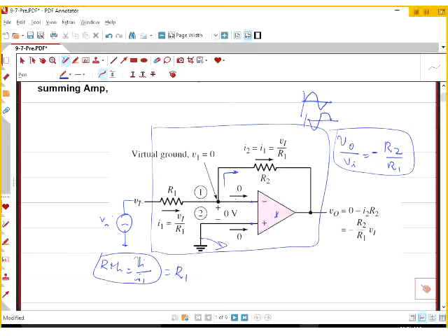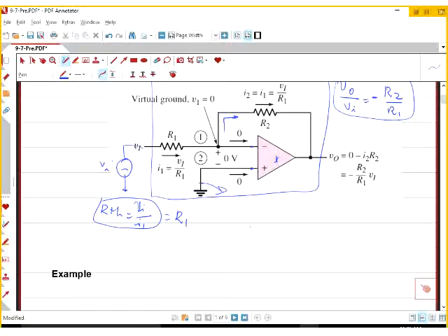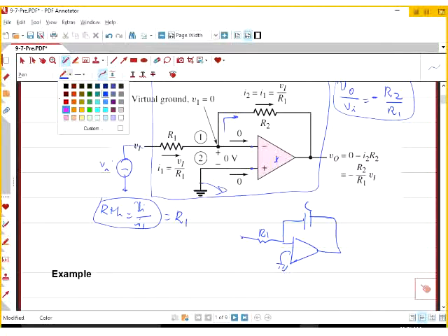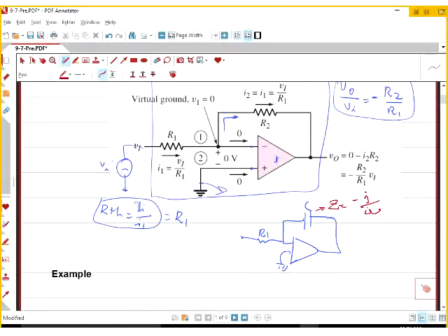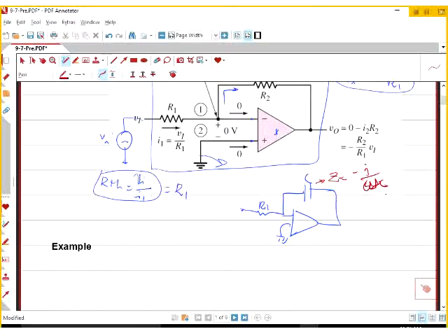And you know, these equations are correct not only for resistance. So if I have this circuit with a capacitor, exactly the same process, same equations, nothing changed. The only thing changing is that for C, the impedance is minus j divided by omega C. Let me clean here.